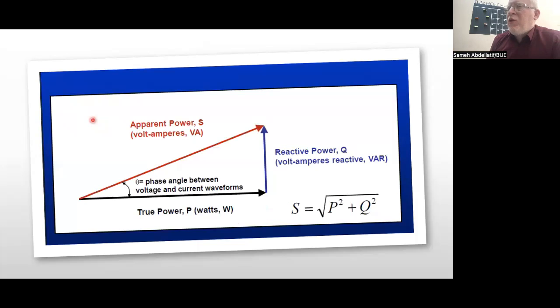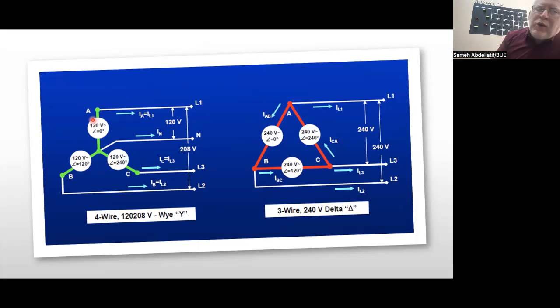In AC signals, I think this is general information that most of you, regardless of your background, know: an AC signal can have two shapes. The first is what we call a single-phase AC signal, and the second is a three-phase AC signal. That's why when you go to the market to search for DC-AC inverters, you will find two types. You can find a single-phase inverter, which means that your output is in the form of a single phase, normally a 220 volt standard, or a three-phase inverter that generates a three-phase voltage, commonly used in either a star or a delta format. As this course is a multidisciplinary course, not targeting mainly electrical power engineers but different engineering directions, we are not going into deep details related to that. However, you can search for more details about three-phase and single-phase inverters.